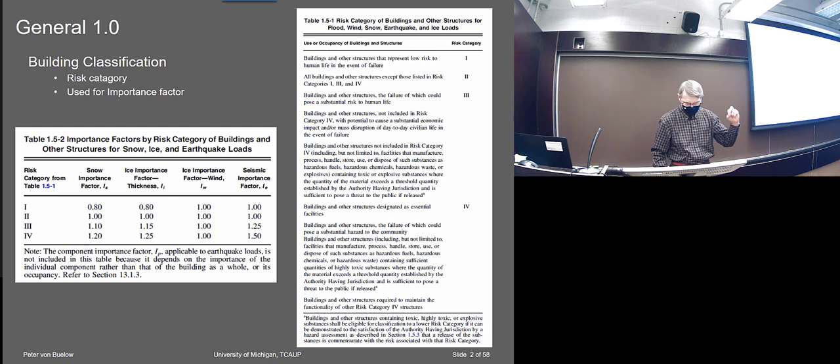When we determine the loads, except for dead load, which pretty accurately represents the actual weight of the structure, the other loads are kind of your best estimate, because you don't know precisely what the wind at your particular location is going to be, or the 50-year worst snow maybe. In some details, it's a little bit of a guess.